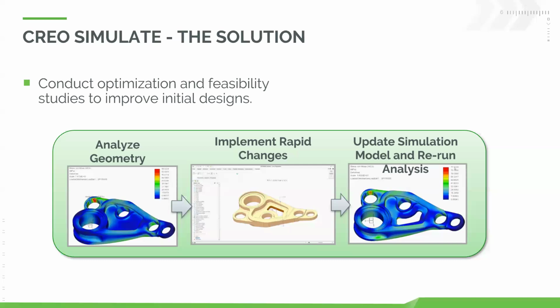This will actually allow you to set up studies with goals in mind. And that goal could be, I want to decrease the stress in a certain area without compromising on, of course, structural integrity. And I want to be able to manipulate my features, like the dimensions of something, the length, the round, the thickness of something.